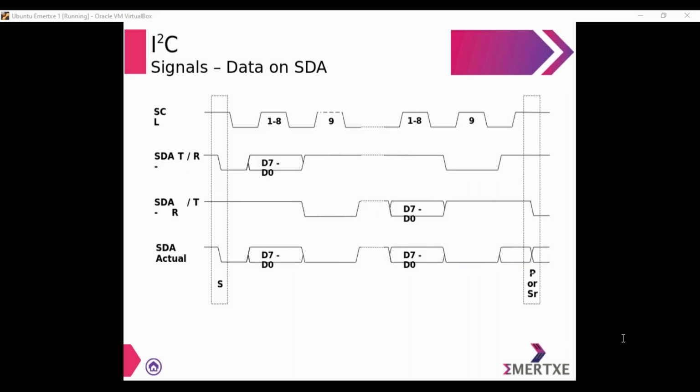You said the stop bit is when the clock is high and data rises from 0 to 1. But where is it in the diagram? So you can see the clock line is high. If it is a repeat start, you transmit a start bit when the clock line is high. Let me highlight here: the clock line is high.